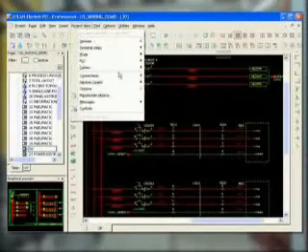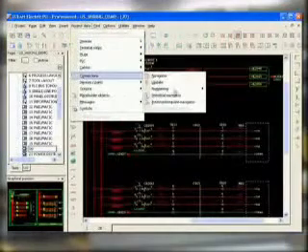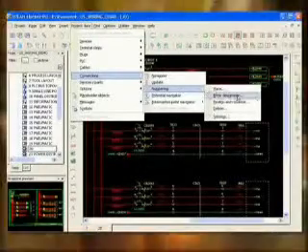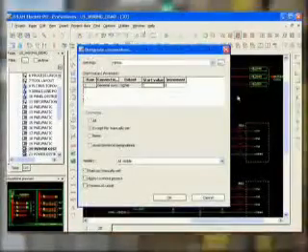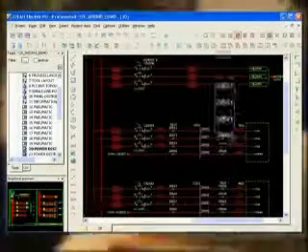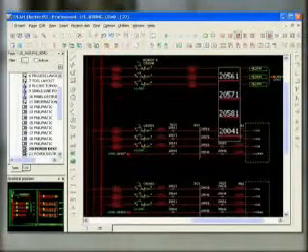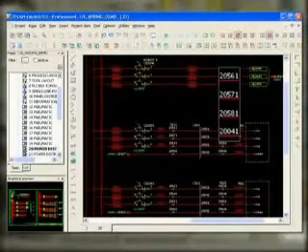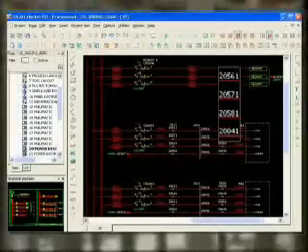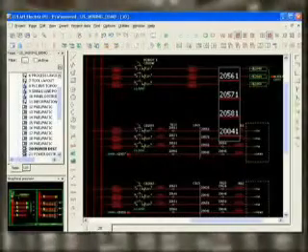To automatically number the wires, go back to Project Data, Connections, Numbering and enter Designation. In the Designate Connections dialog, set your preferences for numbering. Eplan will automatically number your connections based upon the numbering scheme selected previously. In this example, the connections are numbered by page, row and counter.